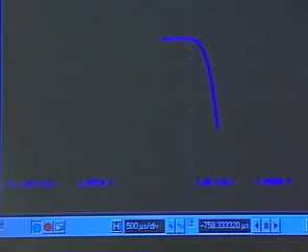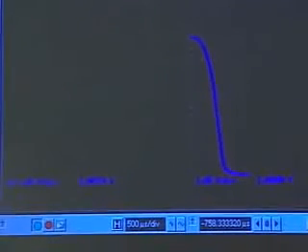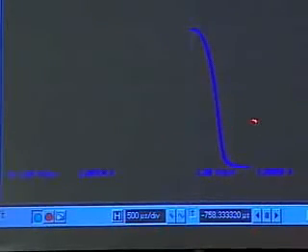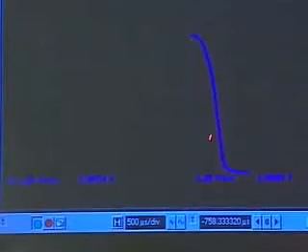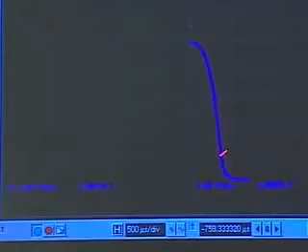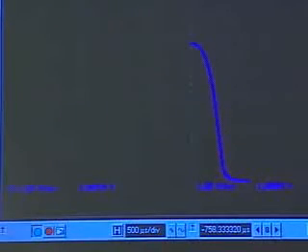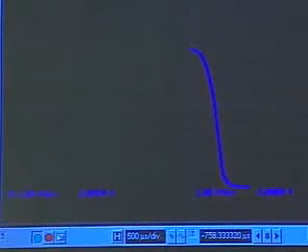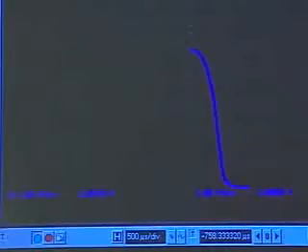Okay, so the MOSFET is in saturation, things are going great. As I increase my Vi, notice at some point, I begin to go out of my saturation region in the MOSFET, and somewhere here, I go from the saturation region and transition into the triode region, and this value shown here gives you the corresponding input voltage and the output voltage.